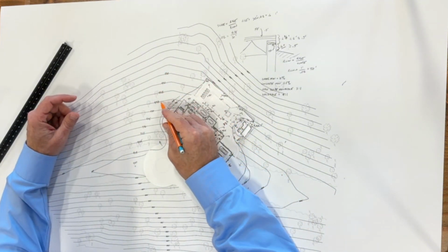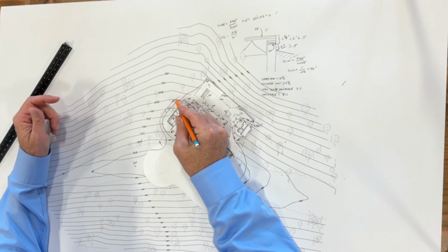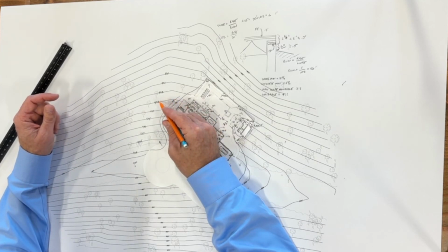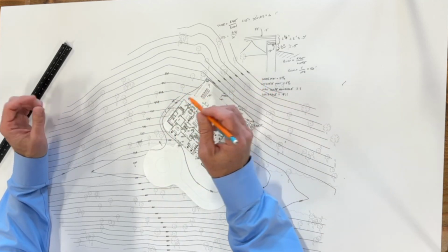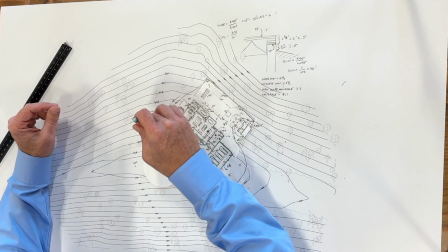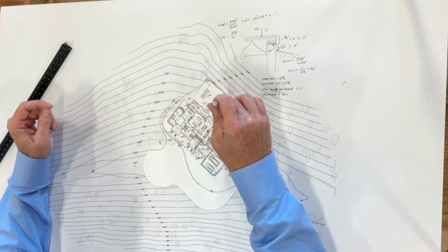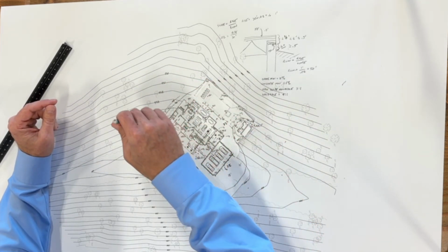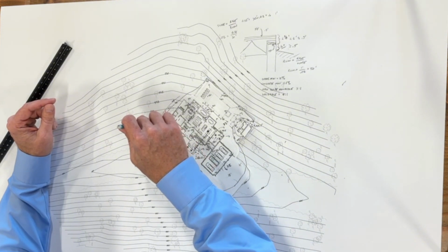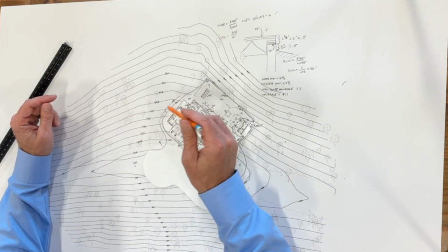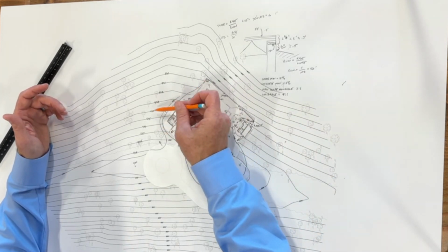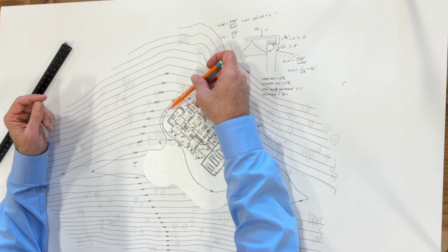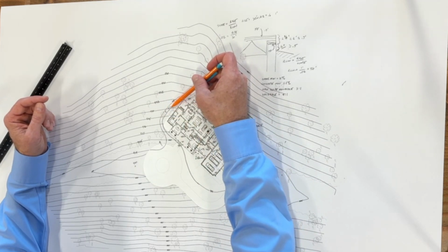Okay, that's a 933, which means there's a 6-foot drop right now from there to there. And the other thing is you can see trees that are right here. So anytime you're making elevations go across a tree, that means that tree has to go. So that's another reason why we might finish this and then change this. Like we might say, I don't want to lose these trees, and so I'm going to make this a 3-to-1 instead of a 4-to-1. And so you adjust.